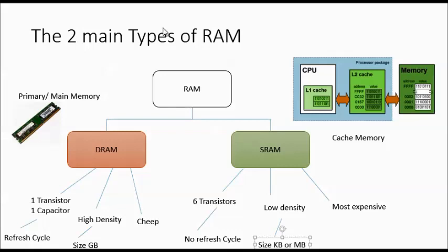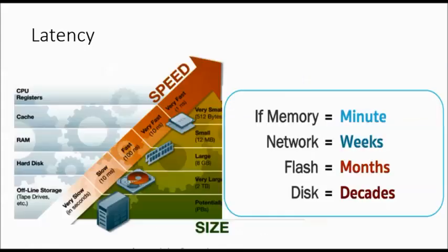So because the sizes are extremely limited, it's not appropriate for us to use static RAM as the main primary memory store. Instead, a solution has come about whereby we store only the most relevant and commonly needed, most recently needed instructions or data in this much smaller but much faster static RAM, known as cache memory.